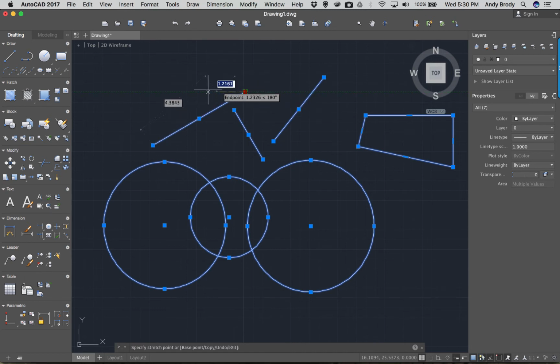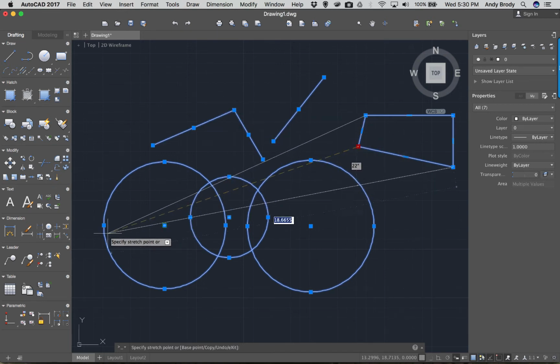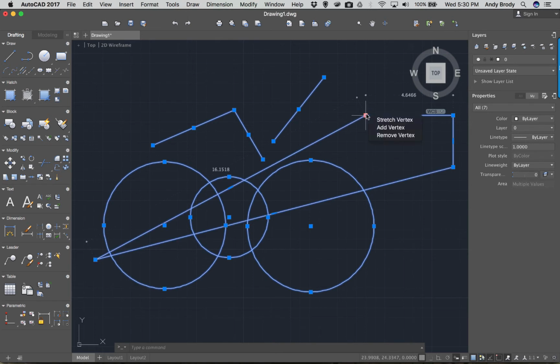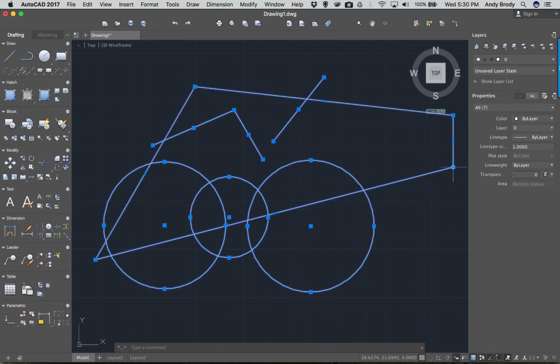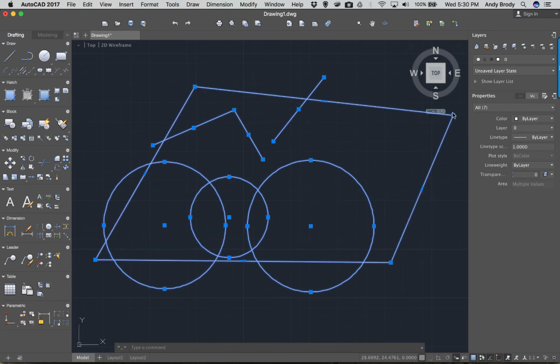This one here at the end grabs it by the very end, and I can move it and try to make it fit to that other line. And the spline, or polyline, I guess it is, will modify multiple lines at once because they're all connected. Okay, so using grips is a great way to edit things in a very simple manner.